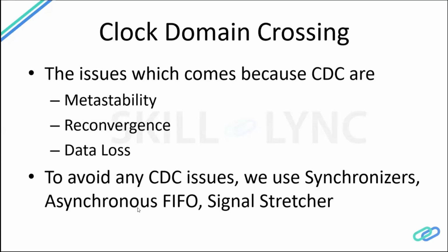So how do we select whether to use a two flop synchronizer or a three flop synchronizer? It depends on how the signal gets stable, which is decided by the process or the technology we are running. Whether the design is 5 nanometer or 7 nanometer, or for that matter 15 nanometer or any nanometer, the signal stability will vary depending on the technology. So in that technology, it might be that a two flop synchronizer is needed, or four flop synchronizer, sorry, three flop synchronizer. Based on that, we use a synchronizer.